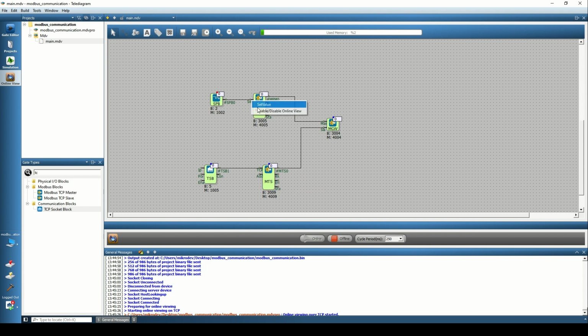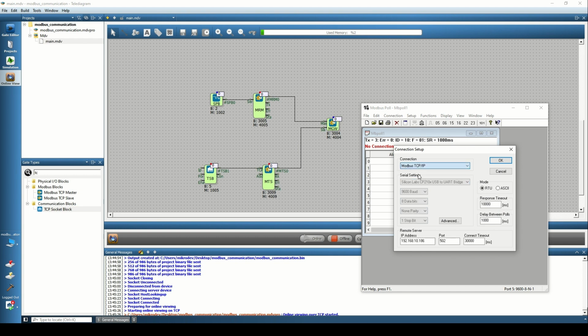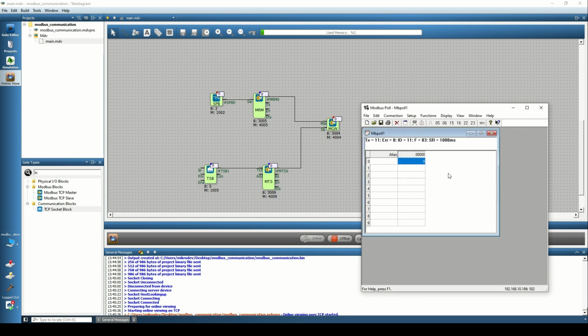After loading this project, let's establish the connection of the device. I'm connecting to the device via TCP/IP from port 502. There are energy analyzers at addresses 11 and 12 now. We will display this here. I made the slave ID 11. Let it start from address 0. Since they are word variables, it's the first energy analyzer. All the data is coming. I even increased the quantity to 40. As displayed, there is a value in all the data. This was the device with ID 11.